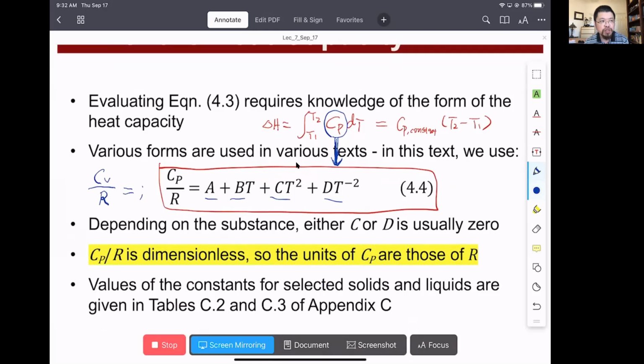Well, that was a choice made when people were talking about the Cp and Cv dependence on temperature, and especially when they were trying to measure all those coefficients A, B, C, and D, they found that it's a little bit better to look at the equation itself, especially since those coefficients have a multiple factor of R. So that is simply a mathematical choice of expressing the left term as Cp over R, not Cp itself. Right? So that is a side note.